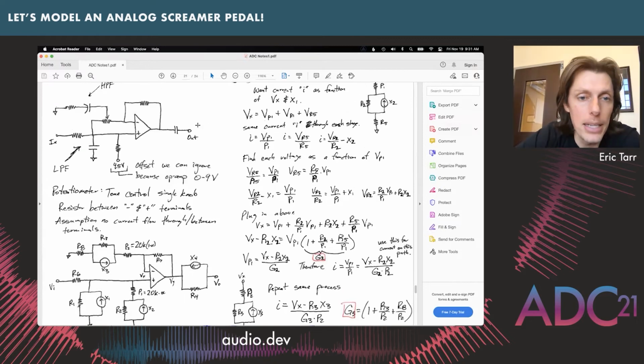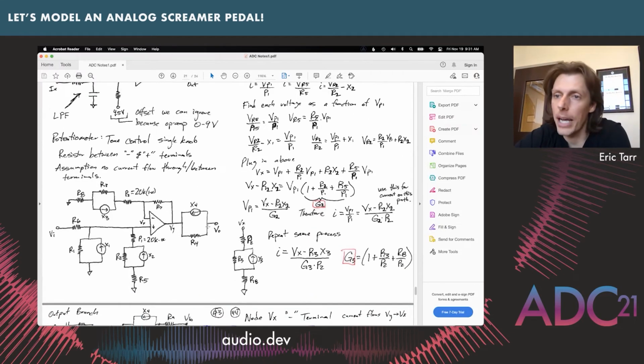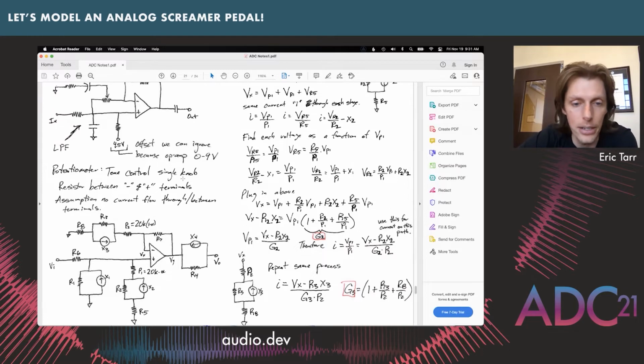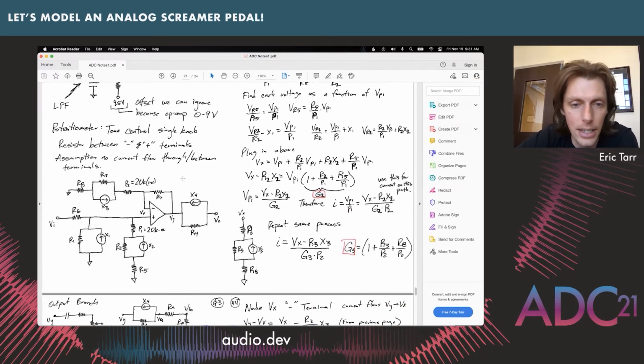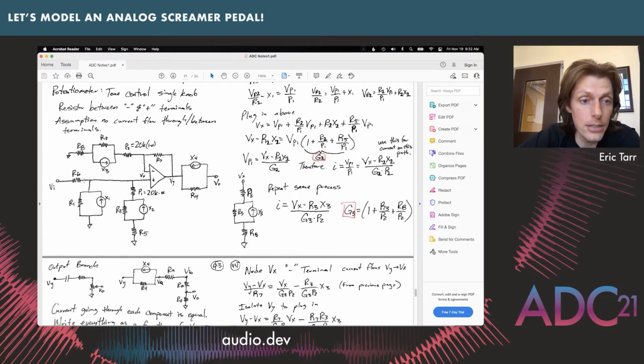And then I made a substitution over here for our capacitor. Technically, this capacitor is supposed to handle the DC blocking of this 4.5 volts offset, but we're not using that 4.5 volts, but we'll leave the capacitor in there. Okay, so this is a complicated circuit to try and analyze, especially based on what we've covered very quickly.